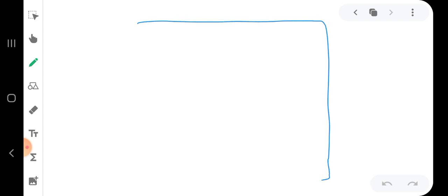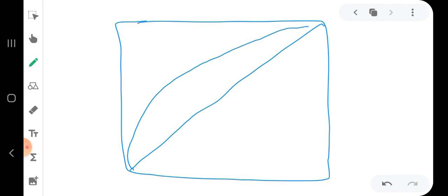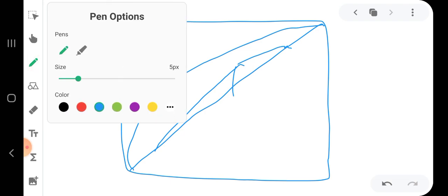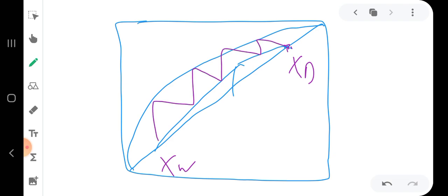In order to explain this equation, let's draw a McCabe-Thiele diagram. So we have the 45-degree line, and this is the equilibrium curve. For example, we have this operating curve, this q-line, and then this bottom section line. And then we start counting the number of stages. So we start here from xd until we reach xw. So this will be 1, 2, 3, 4.